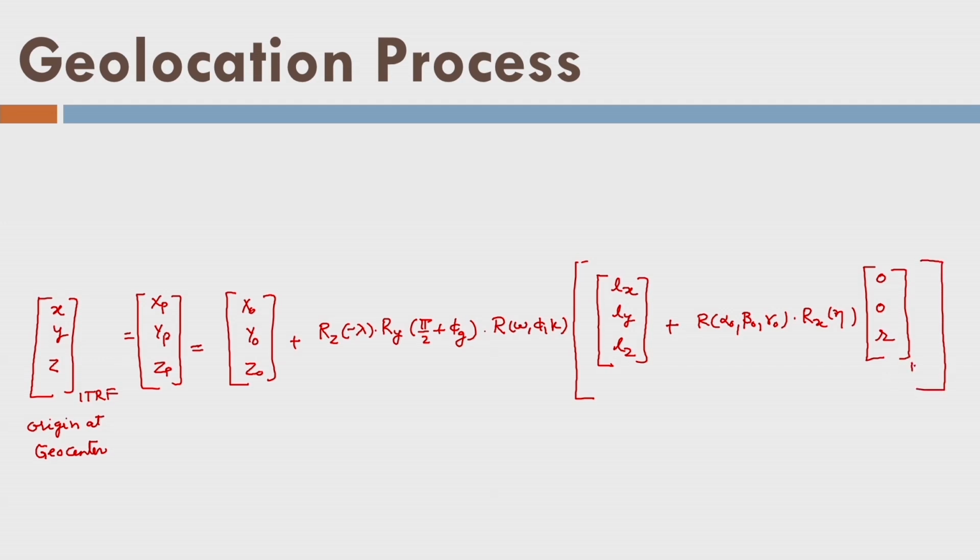I would like to indicate that the measurement was in the instantaneous reference frame. This is the rotation between the instantaneous reference frame and the scanner reference frame, and this is the rotation between the scanner reference frame and the body reference frame, and then we measured this lever arm offset in the body reference frame, and finally, this whole quantity was in the body reference frame.